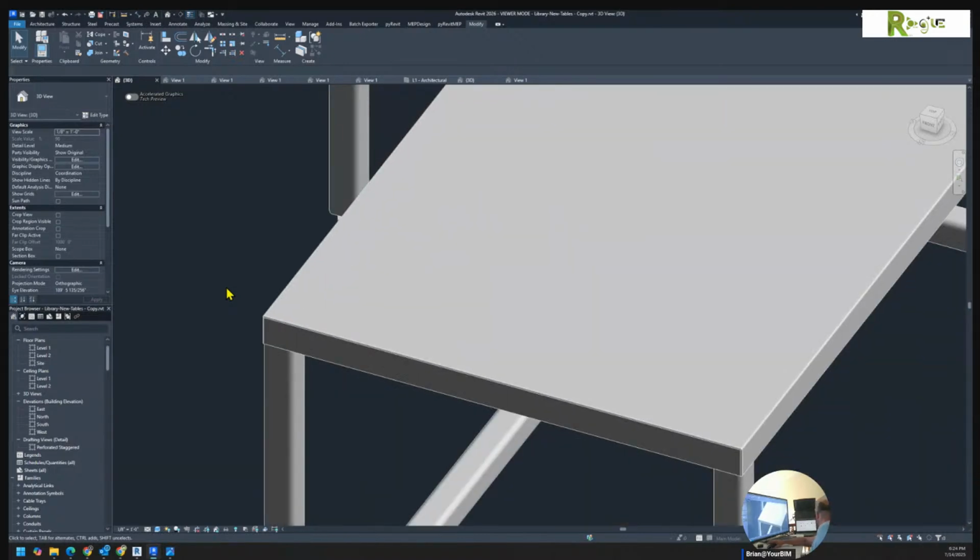I was looking up voids because I'm trying to figure out the size of the families, because our families are high. It said that voids do make a family larger, but you could limit the use of voids. It said, create specialized void families. When voids are needed to cut different element categories, consider creating a generic model void family with the cut with voids when loaded option enabled.